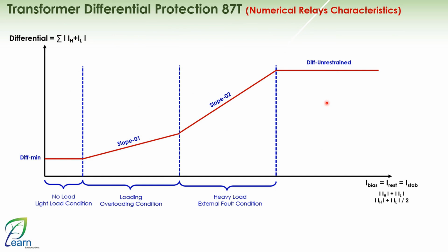Let's assume, to make it easier for ourselves, that the bias current is a sum of algebraic currents. Very nice, that's great. Now what will be the maximum value of the differential when both currents have an angle of 0, meaning they are combined together algebraically?